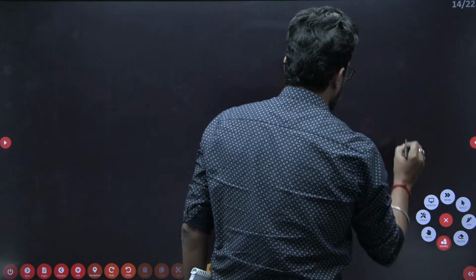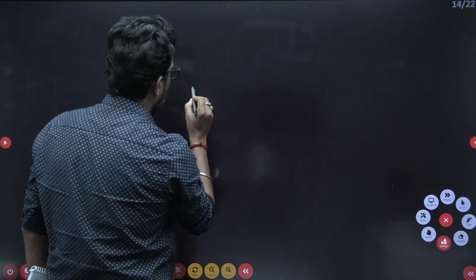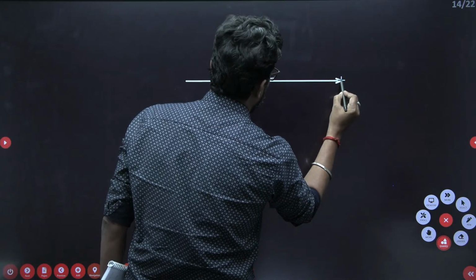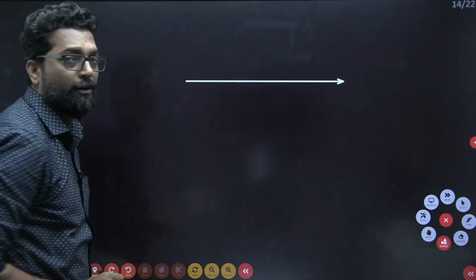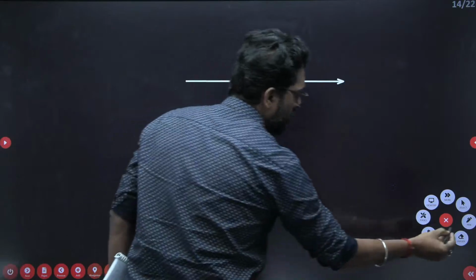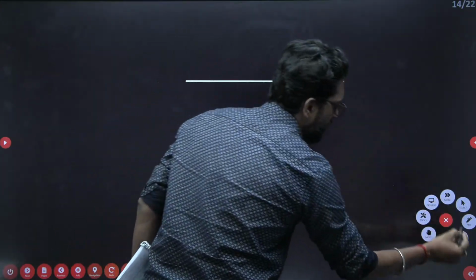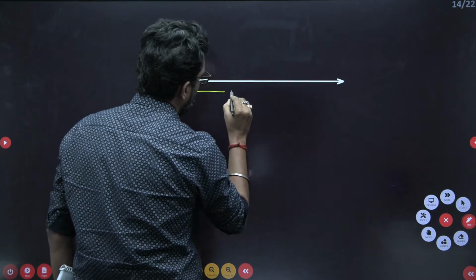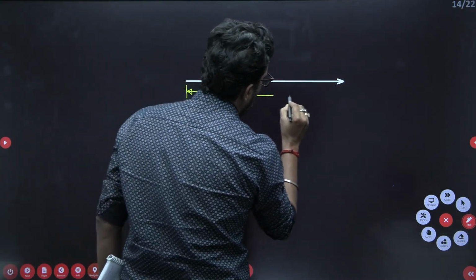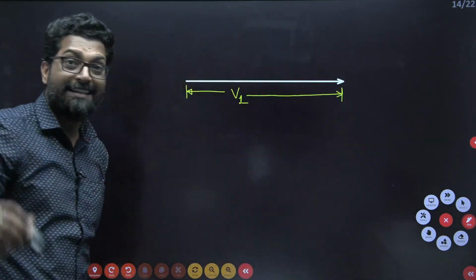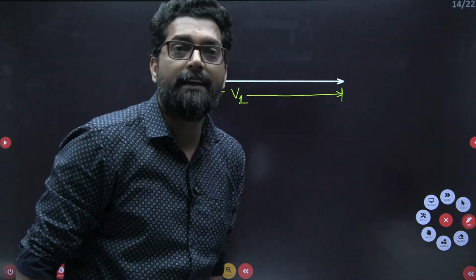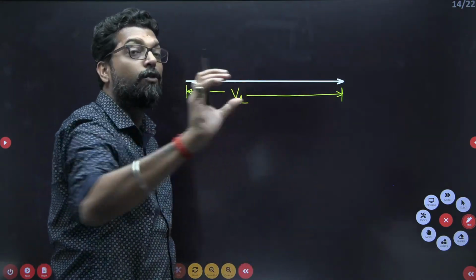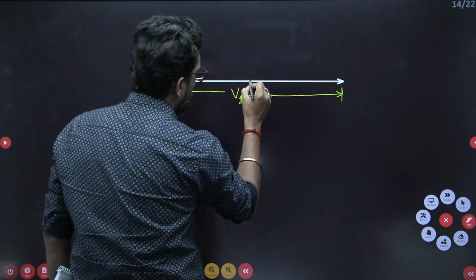So this is your inlet velocity. You have to draw the inlet velocity triangle. It is in a straight line. This total magnitude is your V1. From here to here, this velocity V1 is the velocity which is the swing from the nozzle, and the nozzle is fixed. In the case of a Pelton wheel, an impulse turbine, this V1 velocity is your fixed velocity. Now, we have to split it into two parts.